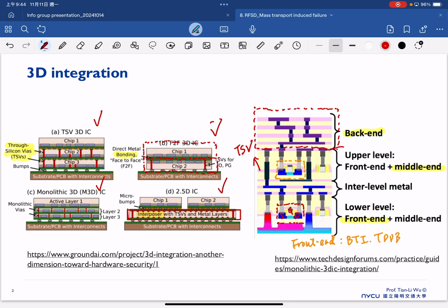So imagine you have electrons starting, a signal starting to flow from here to here to here. That's our electrical signal here. And we will have the output bias, for example, like VDD1. And we have another bias like VDD2 here. These different VDDs are going to provide the signal to our transistor, to provide a bias to our transistor. But at the meantime, because of your bias here, the electrons will flow here. Your bias here, another electron will flow here. And these actually will start to create certain reliability issues.